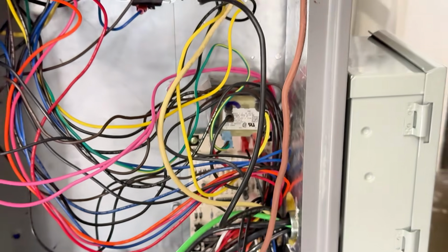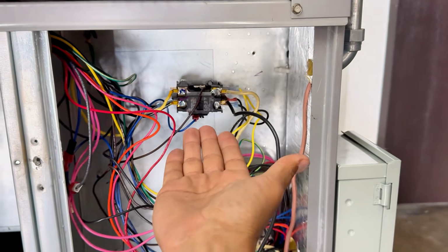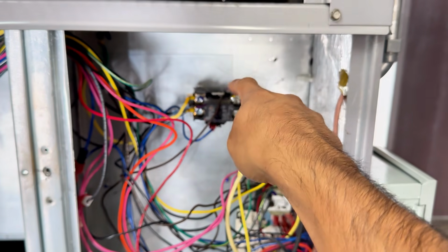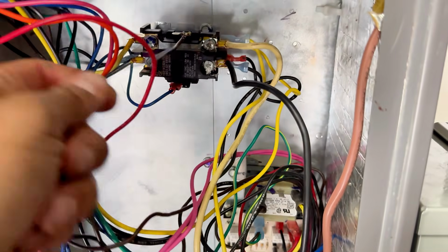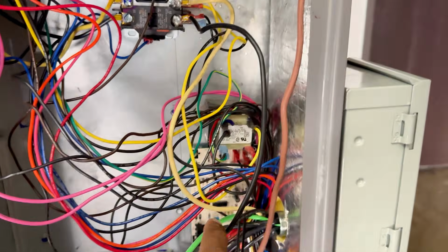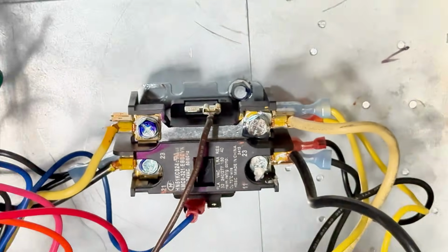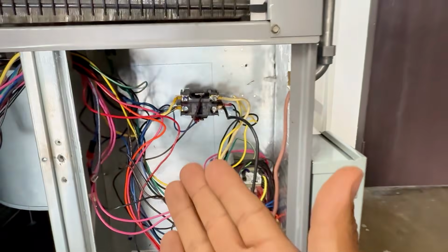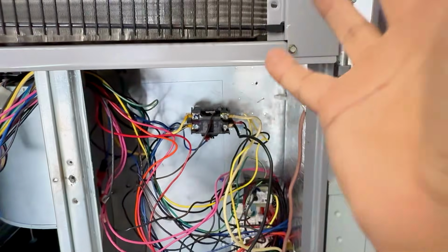So what I'm trying to teach you here is that there's different ways to send your 24 volts, right? There's different ways that the 24 volts can travel to make it to the other side of the load, because Peach is already here. Common is already there. Common is always home run. If you were to follow this brown wire, that's your common. So let's see, if I follow that wire right there, yep, it goes to all my commons, and then the common coming out of the transformer confirms it because it's a brown wire coming out. The common on that one, you see, brown wire. And sure enough, it does go to the common. But this is the other way. Mario, or the 24 volts, you can bypass it. It will turn it on, but that's not the right way.